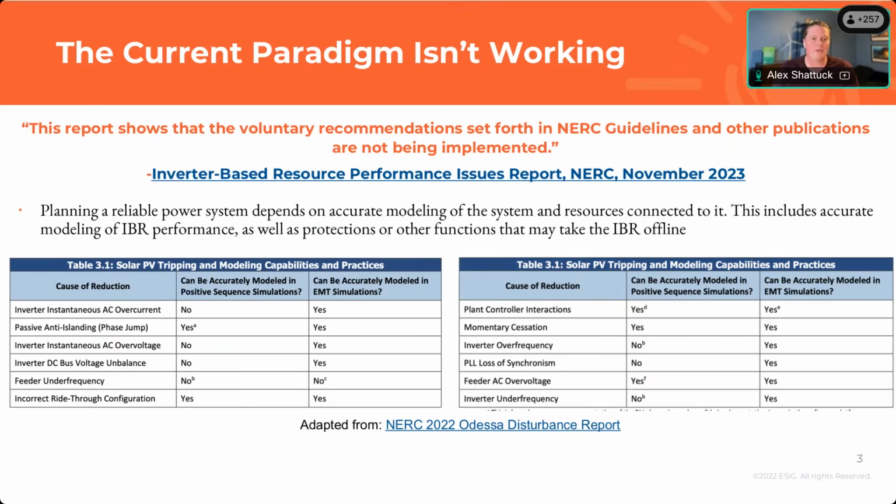So planning a reliable power system in general depends on accurate modeling of the system and everything connected to it. What I'm going to focus on here today is modeling IBR performance, so the actual inverter-based resource, the wind plant, the solar plant, the battery energy storage plant, modeling themselves and their performance, and their components like collector systems, transformers, cables, substation equipment, and anything that may take that facility offline.